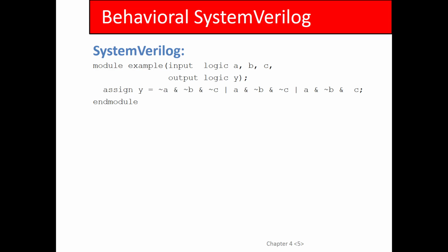Make sense? Now the first thing you probably notice from this is, where are the curly braces? There are no curly braces in Verilog. There are, but they're not used to define scope. They're used for bit twiddling, which I'll get to in a minute. But there are no curly braces that define the basic blocks in this language. Kind of weird, right? Module and endmodule define the beginning and end. And also there's a semicolon after the module line. That's kind of weird, right? You don't do that in Java. You don't do that in C++. You don't put a semicolon there. Also, no semicolon here.